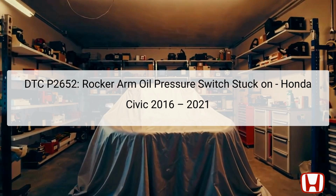The diagnostic trouble code, DTC P2652, indicates that the rocker arm oil pressure switch is stuck in an on position, which can lead to excess oil pressure problems in the variable valve timing (VVT) system of the Honda Civic models from 2016 to 2021.